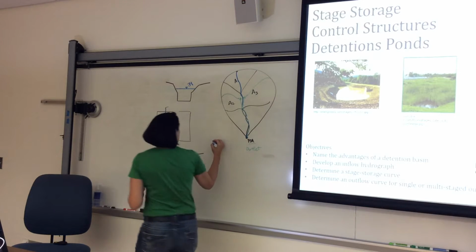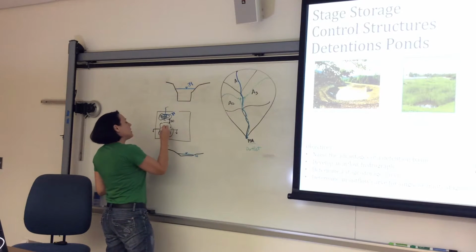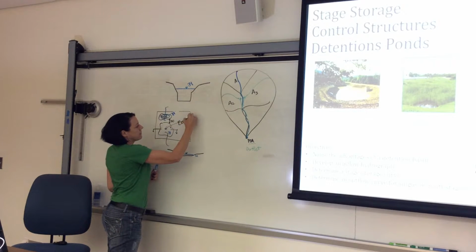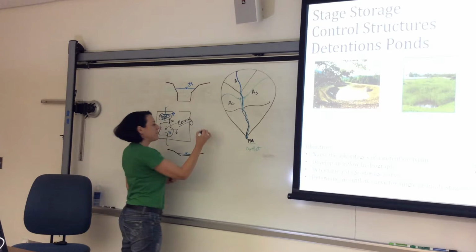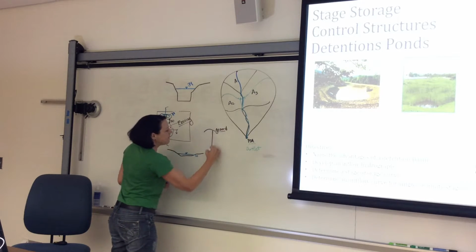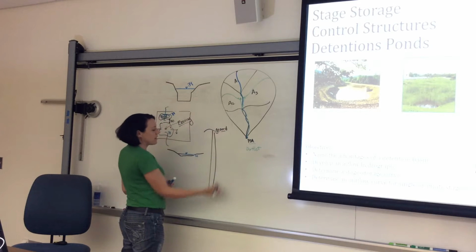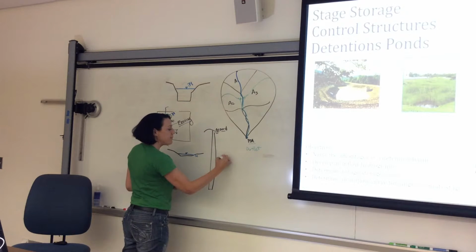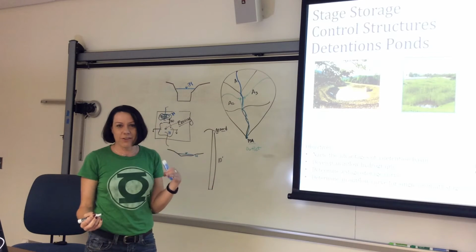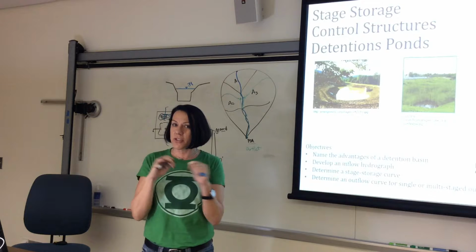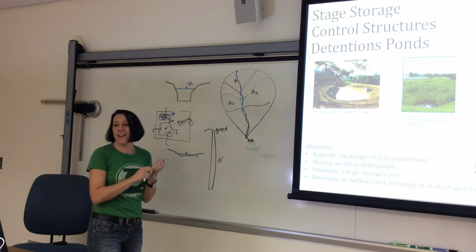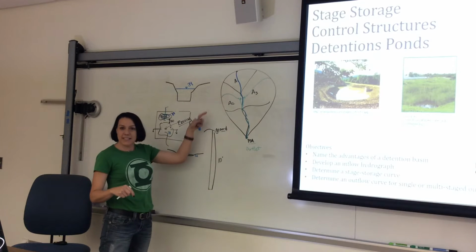So if you did this soil column, let's say I took a core sample or a boring. So this is ground, and I did a huge deep boring in the ground, maybe 10 feet deep. And the reason they're going 10 feet isn't because of the groundwater, not here in Florida. They're going 10 feet to see how good the dirt is that they can use on the site for fill. So that's why they go 10 feet down. They want to know what that depth is.